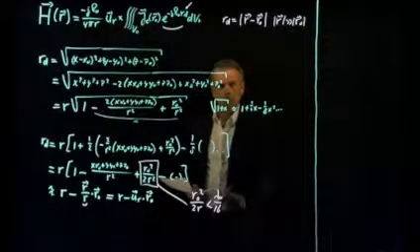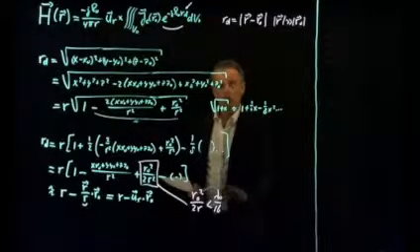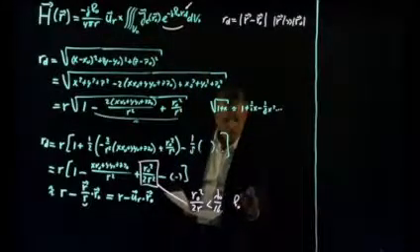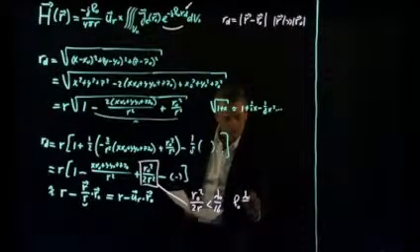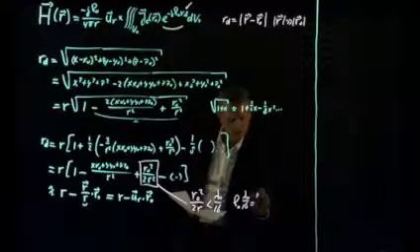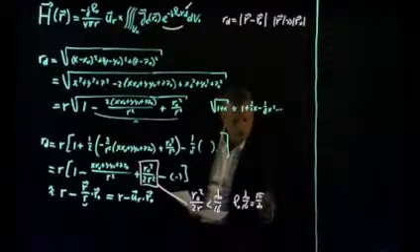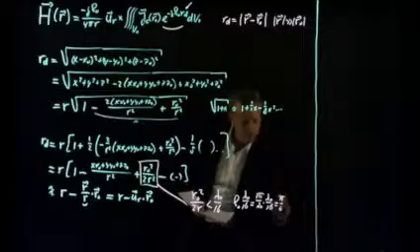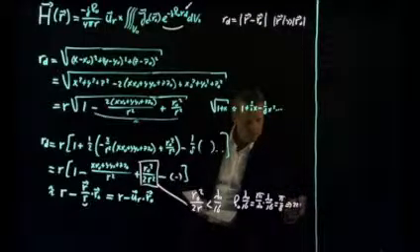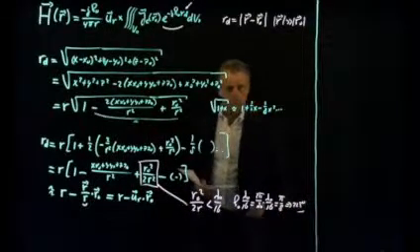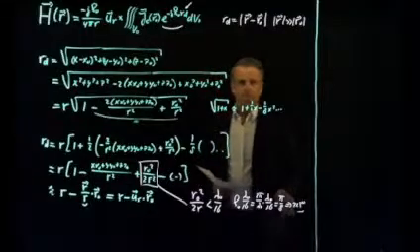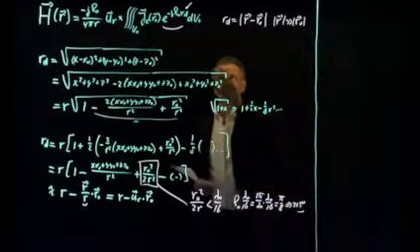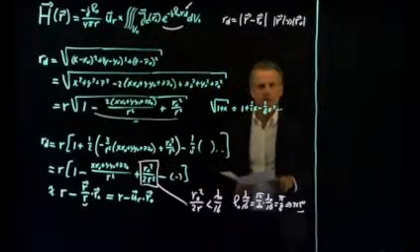If you want to know what it means, you have to look into this argument here. So that means that we have to look at k naught times lambda naught over 16, and that is 2 pi over lambda naught times lambda naught over 16, which is pi over 8, and that is 22.5 degrees. So that means that, worst case, we make an error of 22.5 degrees in this phase term here.